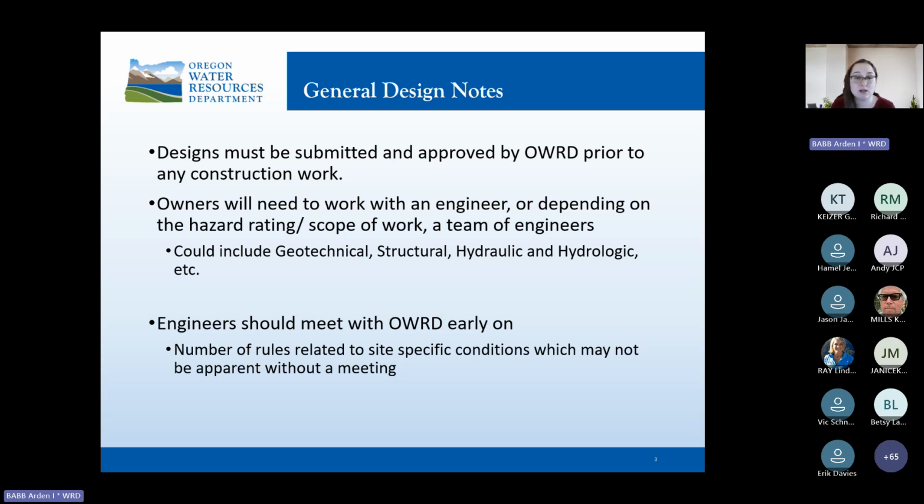Engineers, or the engineering team, need to be meeting with OWRD really early on in the process. There's a number of rules related to site-specific conditions that may not always be apparent without meeting with us and getting some background information on the geology or the location of the proposed dam.